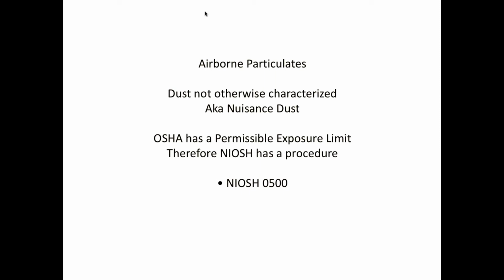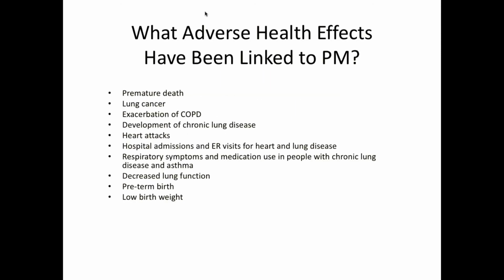There's a whole classification of dusts that are not otherwise characterized. In other words, there's no specific procedure for them based on their toxicity. That's very frequently called nuisance dust. OSHA calls them other dusts that are not characterized, uncharacterized dusts. The procedure for that is NIOSH 500, and we're going to take a look at that.